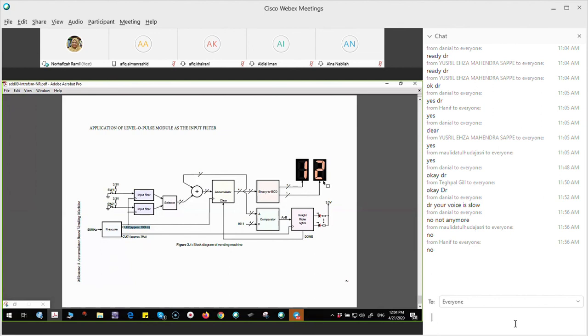If you can group both into BCD it is better, but I think it's not possible to group this one, so that you can see in binary, or when you do quarters, this one will appear as either 0 or 1, and this one in decimal. So this is just display. Actually this is BCD. For this one you would need the 7447, the BCD to 7 segment, so you skip that part.